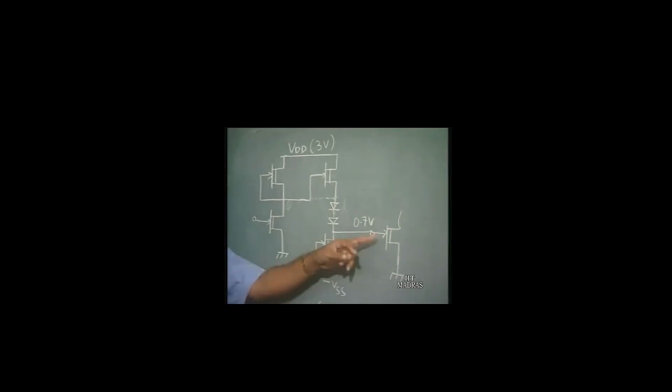So, this is close to 0 volts. So, the gate to source voltage during this switching period is a very large negative voltage, which actually cuts off this source follower transistor. Since this transistor is cut off, there is no current flowing this way. This pull down transistor is of course on, so a current flows out of the input of this output transistor and discharges the input capacitance of this output transistor, and so the output voltage is going to fall.